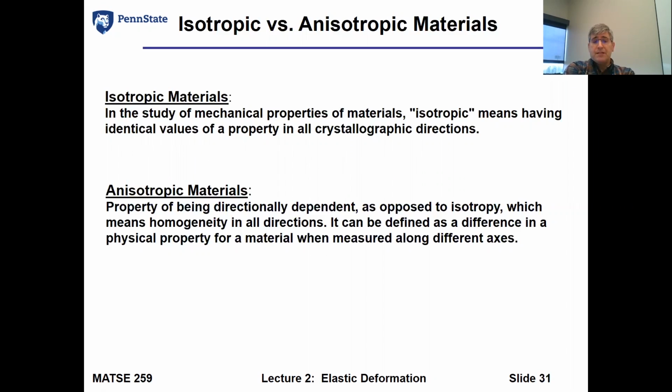What we'll see is that in different orientations they actually have slight differences, so they're slightly anisotropic. It's not a huge difference. It's not the equivalent of what we will see with a carbon fiber composite, where the properties along the orientation of the fibers placed in the composite are significantly different than at a 90-degree normal or transverse orientation to that.